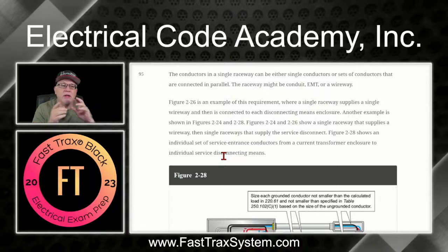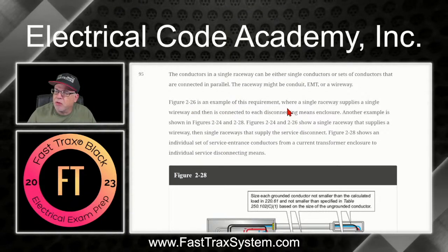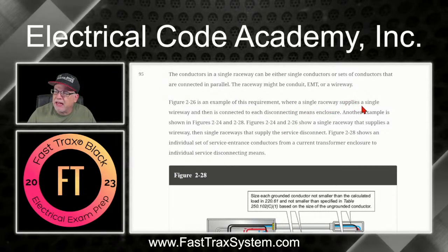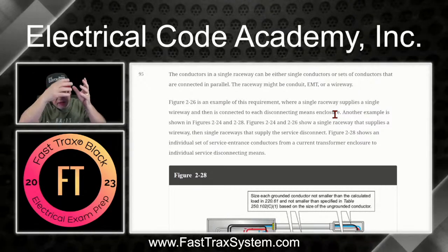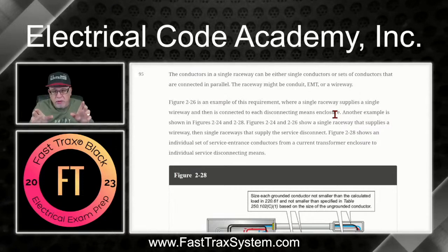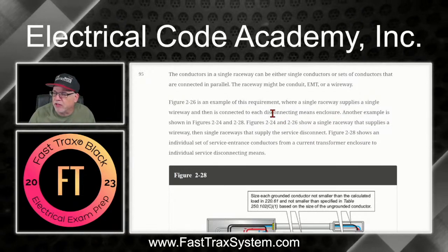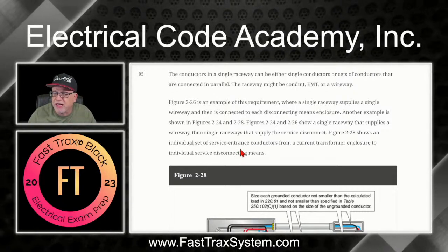It is an example of the requirement where the single raceway supplies a single wireway and is then connected to each disconnecting means enclosure. So it went from one raceway coming in to one wireway, and then broke off to two separate service disconnecting means enclosures. Another example is shown in 2-24 and 2-28. Well, we'll stay at 2-28 because 2-24 is kind of the same scenario.